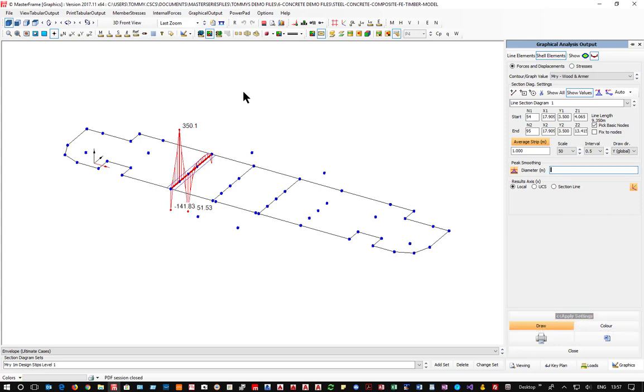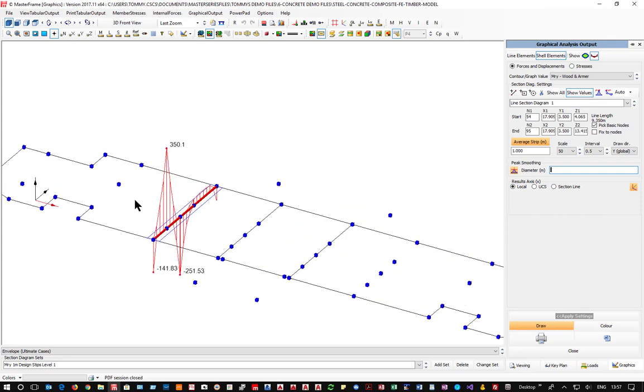And that drops down to 350. Now, in the BS and Eurocode, we can actually take it even wider than that. I was just looking at the Eurocode regulations today, and I couldn't see anything. Obviously, you'd consider a column strip to be half the width, a quarter either side of the column, of the span, of the shorter of the two spans.